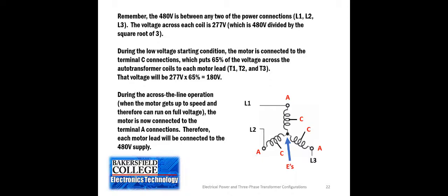So when it's operating on the reduced voltage or the low voltage connection, then you will actually have 180 volts across each coil.